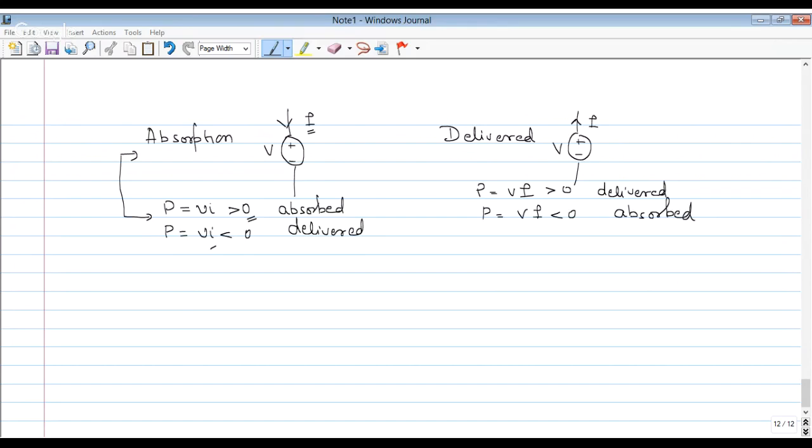Next is from Avinash Dogra. How is the third harmonic component not present in line voltage in delta connection? Avinash, third harmonic or zero sequence is always absent in the line voltage. Why? In delta, you might be thinking line voltage is same as phase voltage. Then why is third harmonic absent? So let me explain this a bit.